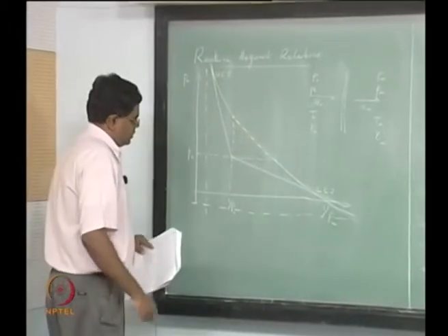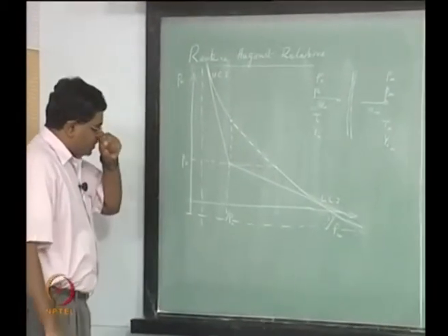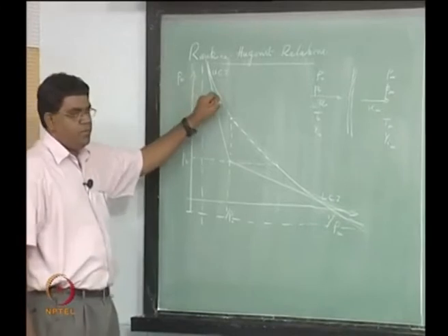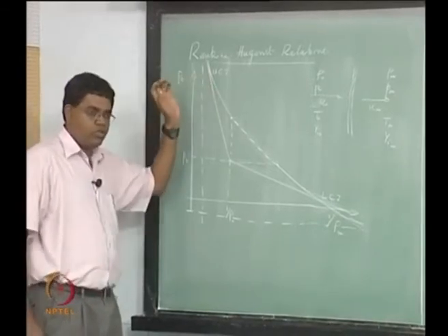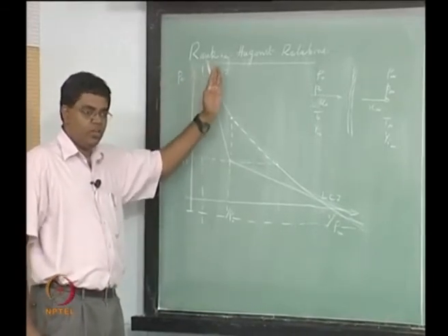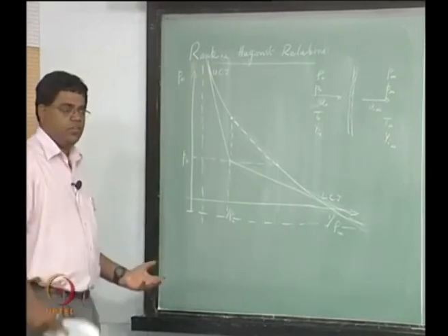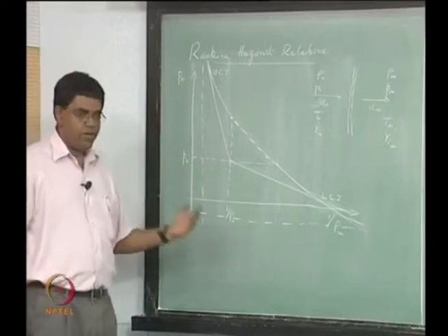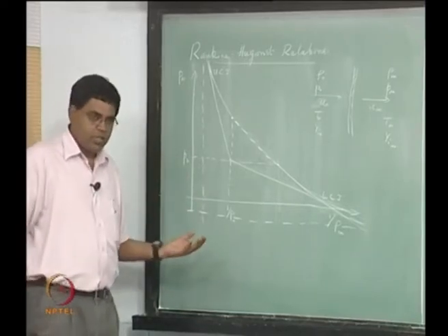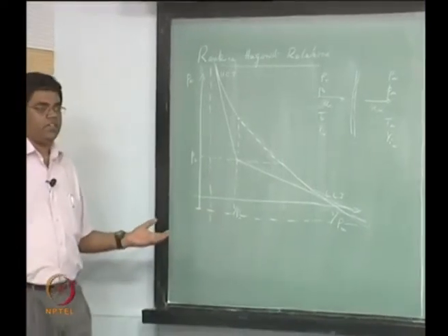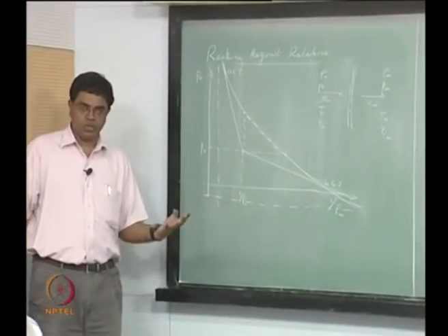Obviously any point that is a solution is an intersection of the Rayleigh line and the Hugoniot, found by solving them together, right? The Rayleigh line has its P infinity and 1 over rho infinity showing up, and the Hugoniot curve has its P infinity and 1 over rho infinity showing up.